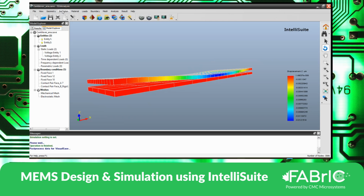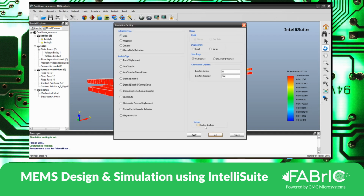Okay. And then there's a question from Almore: for the contact simulation, will we also get the contact area and force? And when we have overdrive, will we know how far we have gone beyond the contact? Yes. If you want to know how far you have gone beyond the contact, then don't check this box called contact analysis. If you want to know where it snaps down, then check the contact analysis.